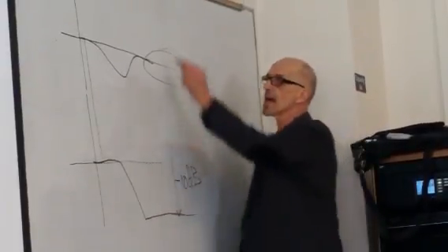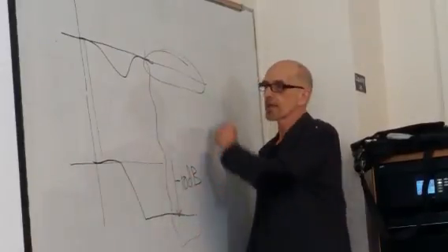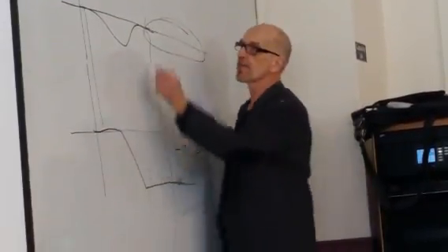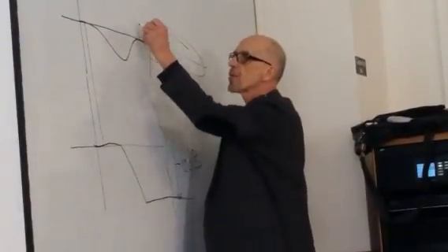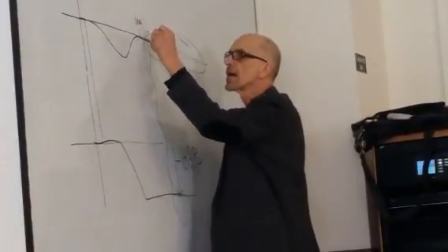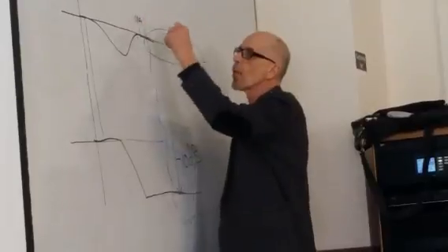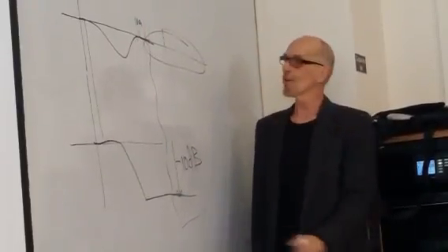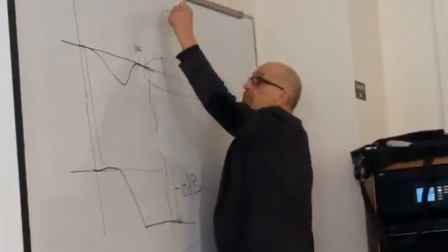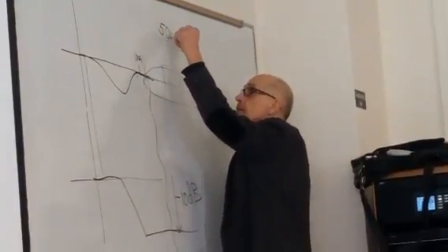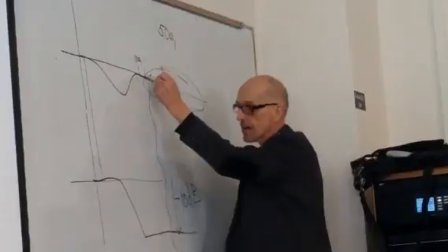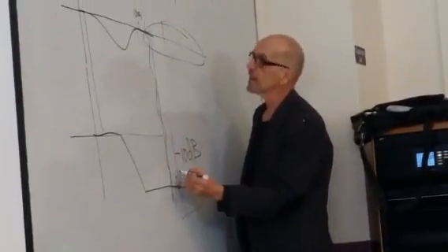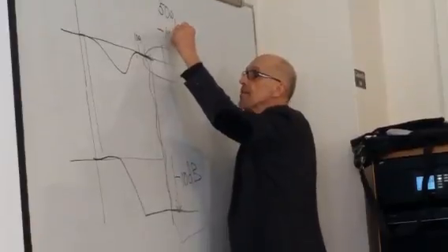So this is the region I'm using my lag compensator in. So what I do is I say, okay, I know this phase is back to 0 at 10 omega 2 or 10 omega 1. I'm going to go to 50 omega 1. And then it's really back to 0. So 50 omega 1 is right here, right? And I want alpha to be minus 10 dB.